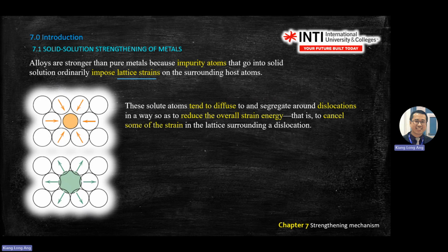Okay, so here, for the solid solution strengthening, again, we have two cases or two mechanisms. One is through substitution, means we find an impurity that's the same size as the host or solvent. But again, if you're following the Hume-Rothery rules, you can either be less 15% or bigger 15%.